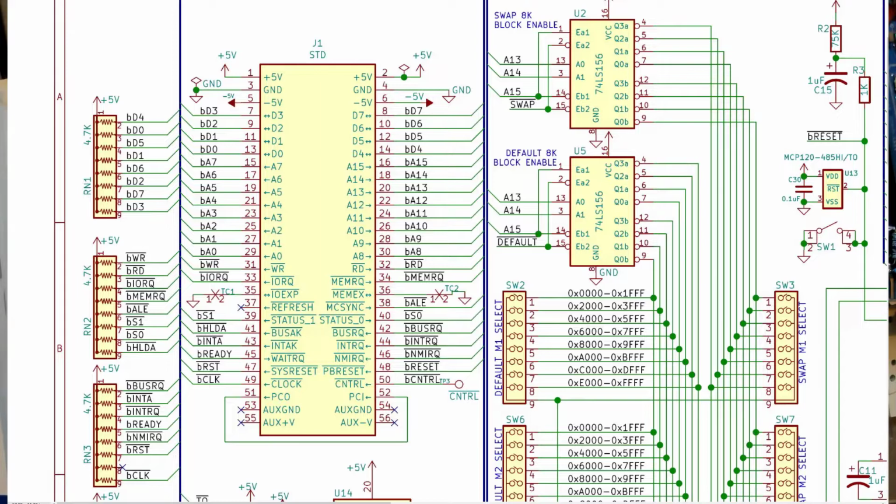So you can think of applications, but nonetheless, I just left them here as a user to tie to whatever they wanted. The next one we're going to ignore is the priority in, and to skip ahead a little bit to one of the output lines we're going to later ignore, we'll ignore its partner, the priority out line now, so we can get it over with. So we're going to ignore both the priority in and the priority out. These are used in a hardwired priority scheme where each card is a lower priority than those connected to its priority in, and that card is of a higher priority than those cards in the chain connected to its priority out. So basically, if the card sees its priority in go low, it means that somebody of a higher priority wants to use the bus. And if somebody else wants to use the bus, this processor should excuse itself.